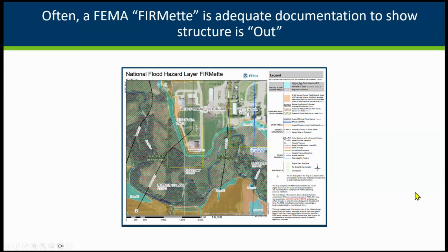So in this case, here's a copy of the FEMA map, and you can see pretty clearly that it is not touching the zone A. If it's touching the 500-year, that medium risk area, that does not trigger the mandatory insurance requirement. It might be a good idea for them to get flood insurance if they're in or touching that 500-year, medium risk area, but it's not mandatory. And if it's not mandatory, they could choose how much coverage they want.